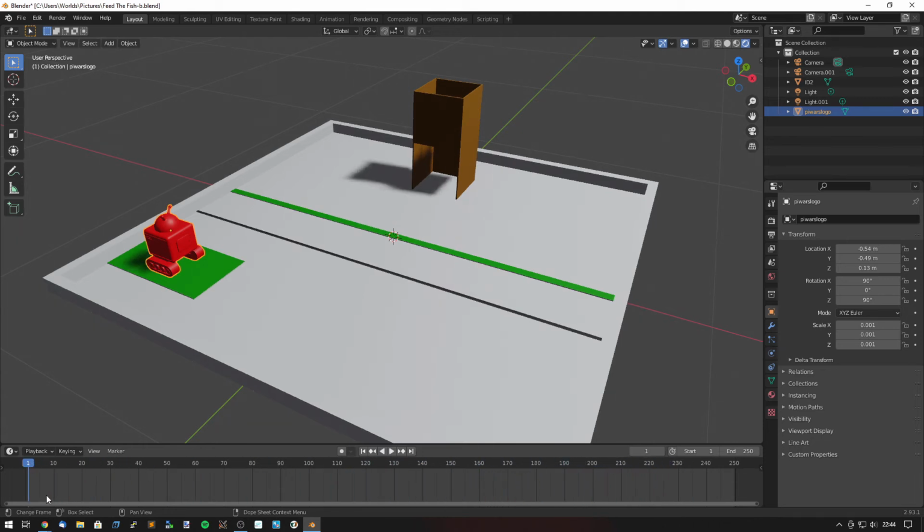If you assume you're working at a video frame rate, that's 30 frames a second approximately. I believe when we export this out, it will be set to 30 frames a second. Then we know that from 1 frame to 30 frames, that's 1 second. From here to here is 2 seconds, 3 seconds, and so on. So that's how we know how long it takes for the robot to go through this sequence.